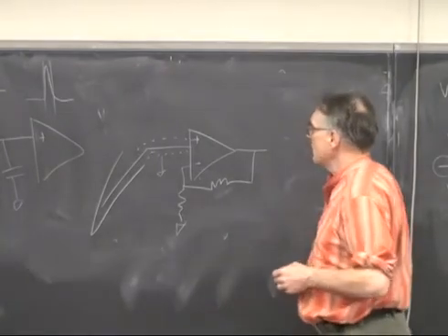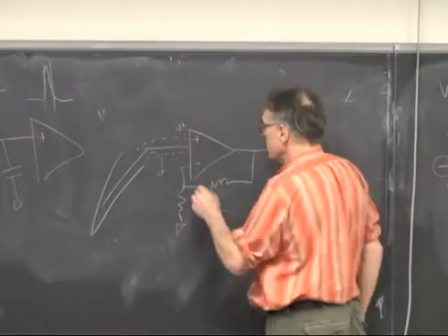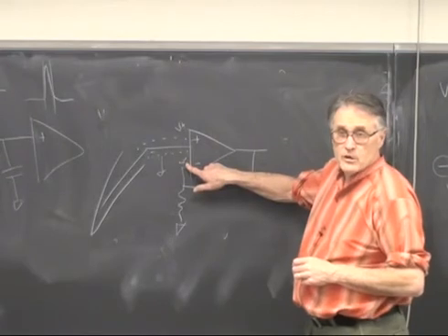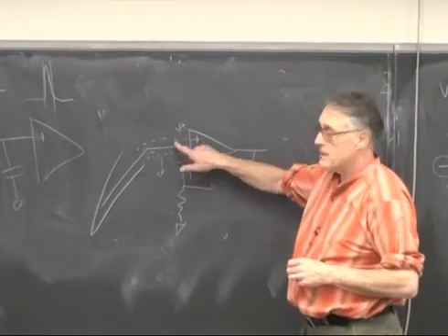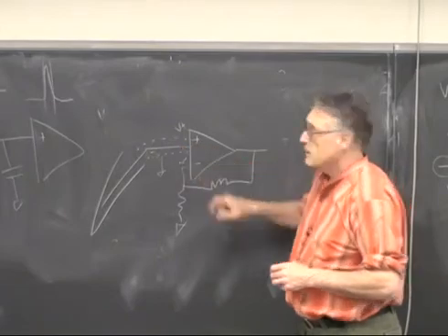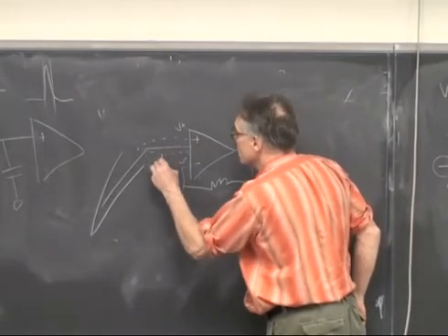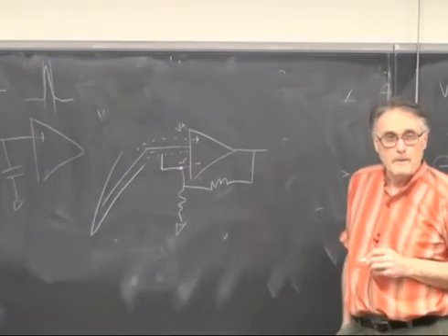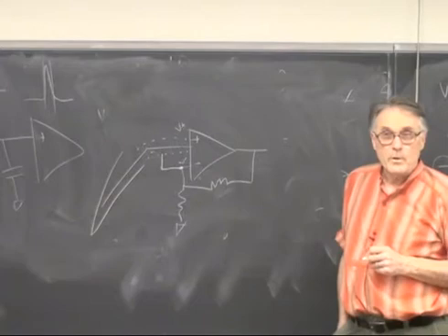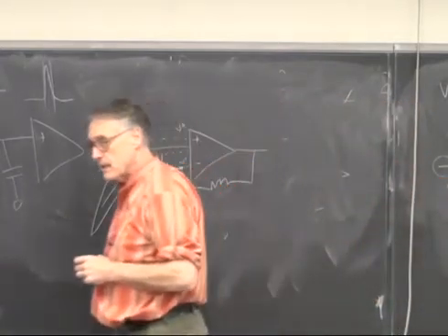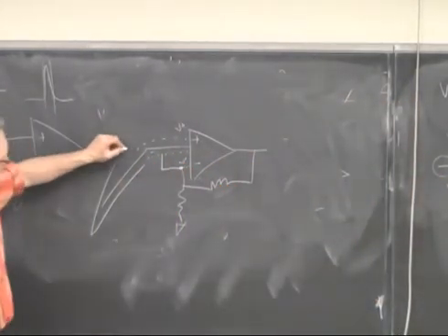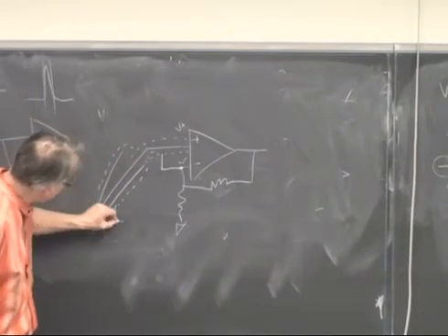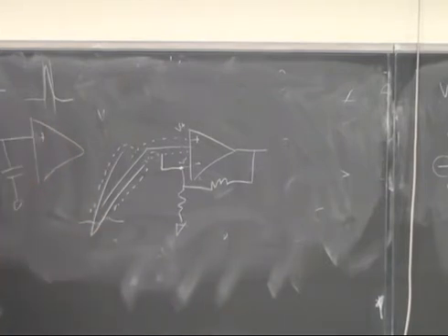But we know this is V plus, right? This is V minus. We happen to have here a source of voltage which is at the same voltage as the center conductor. So why don't, instead of putting this to ground, we hook this shield to the negative input of the op-amp? Now we're guaranteed the voltage on this shield, and we can run this all the way down along the electrode until just before we get to the water, and people do this.